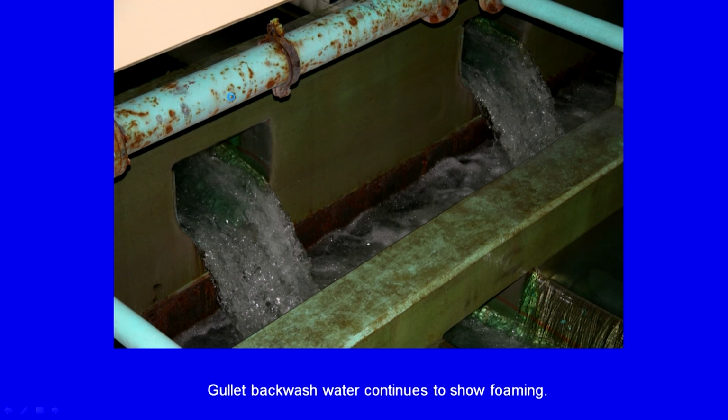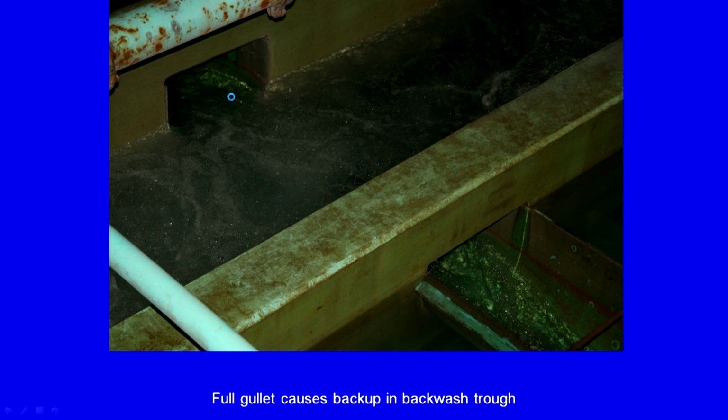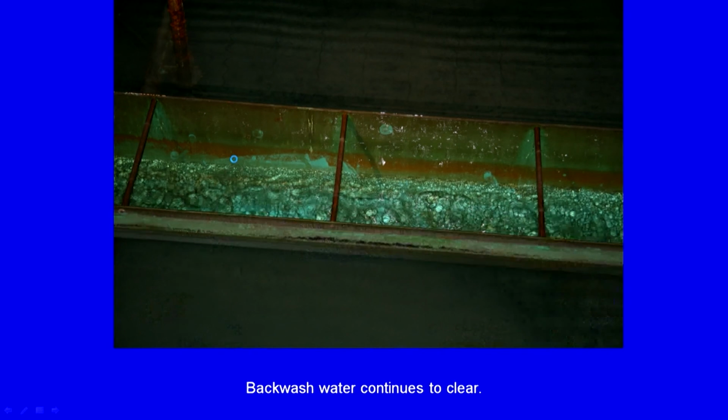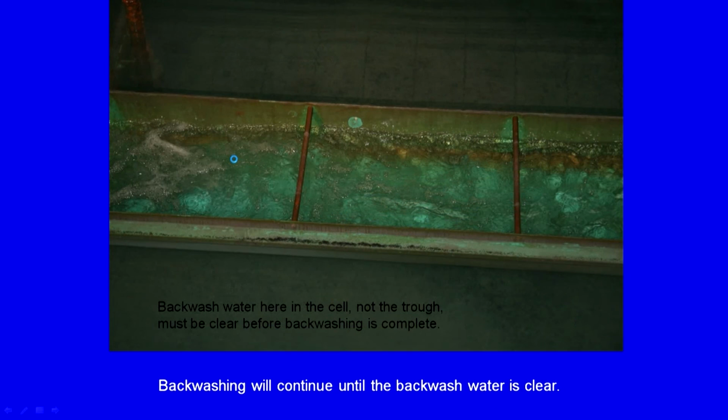And backwash continues to show foaming, which means there is still organic matter that is taking longer to desorb. Backwash now continues to be clear, and looks like in this case the backwashing rate was too high, and that is why it is leading to a backup in the backwash trough. You can compare that with the figure here and this backup. This is something you want to avoid, obviously. So, backwashing will continue until the backwash water is clear. You can have automated ones, but as you can see, even manual backwashing with manual judgment is relatively decent enough.